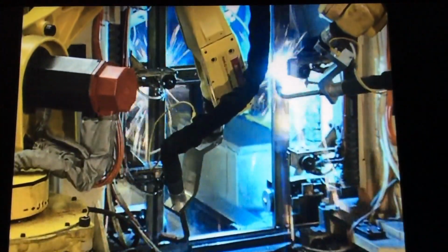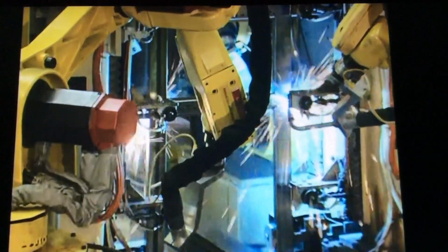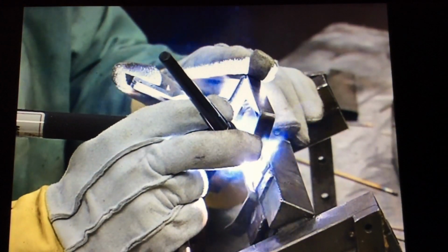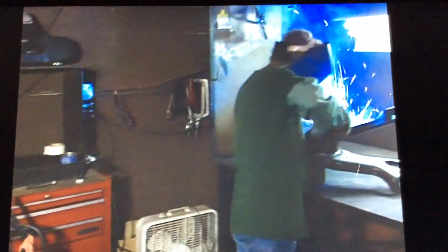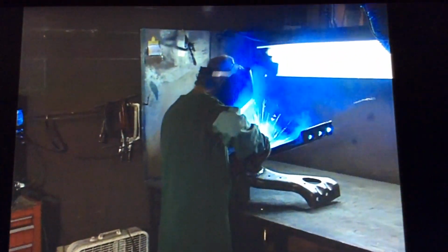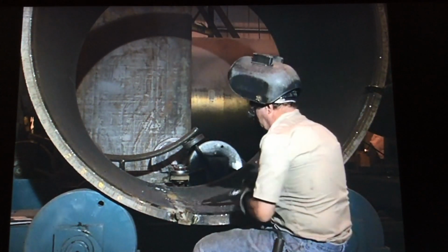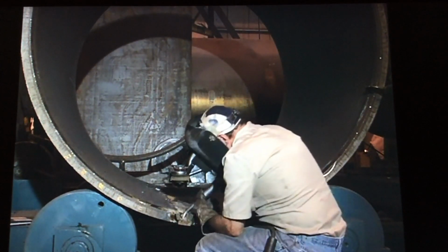The arc is struck between the workpieces and the tip of an electrode. Arc welding electrodes are usually consumable, but can be non-consumable. The consumable electrode is usually wire or rod, and the current that sustains the arc also melts the electrode so that it supplies filler metal to the joint. The electrode may also produce a slag covering to protect the hot weld metal from oxidation.